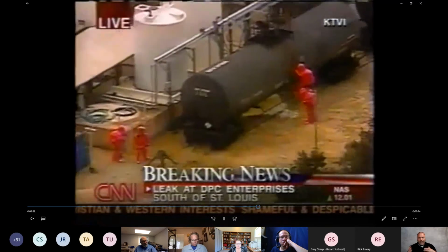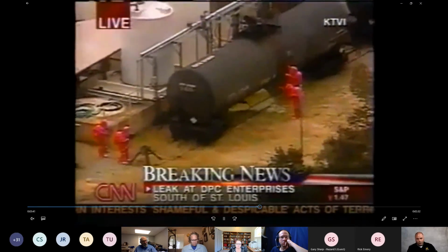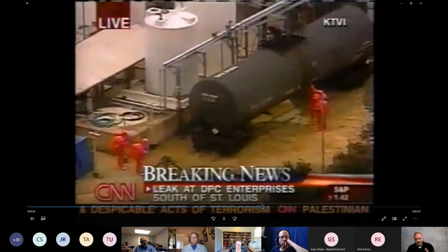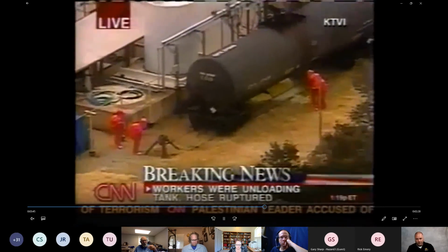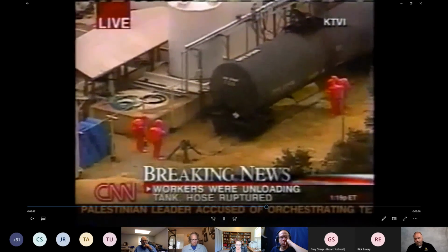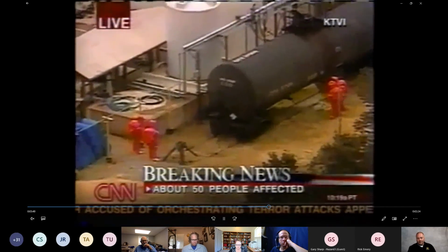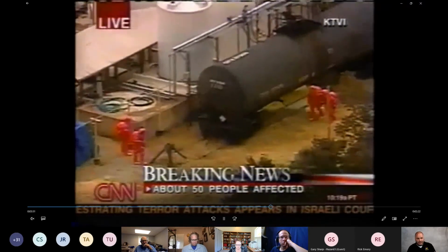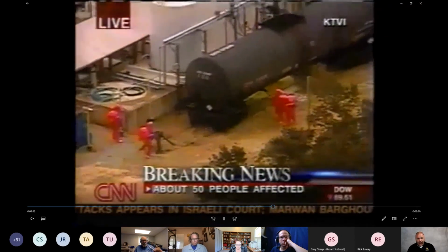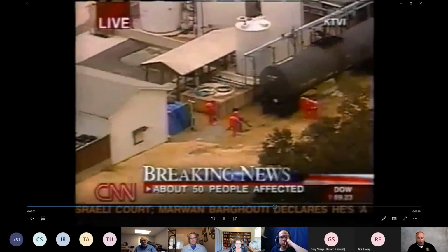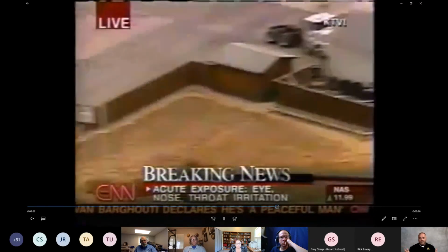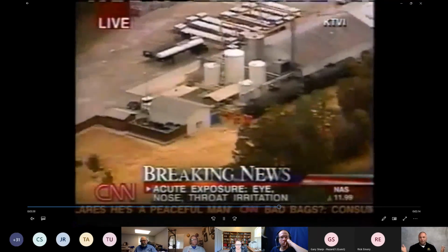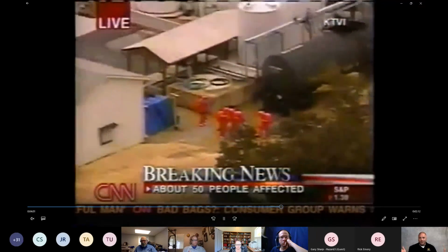I would advocate for, I mean, obviously, if you see a leak, you have a liquid leak. If you smell a leak or your meters are going off, you have a vapor leak. So when you're making entry into this thing, you are dropping those LED things like Christina was just saying at that certain line, which, for this one, is going to be a huge, huge hot zone, exclusion zone.